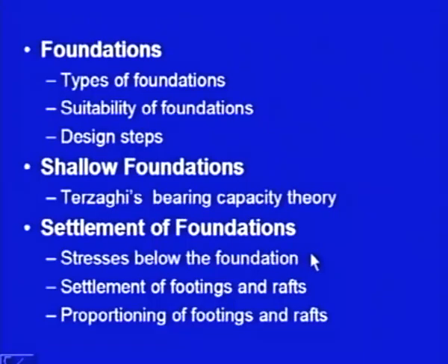For that purpose, we shall need the stresses, that is, how the distribution of stresses takes place below the foundations. Then we shall discuss in detail how to calculate the settlement of footings and rafts, and then proportioning. Once all these things are available, then for a particular type of loading, we will discuss how to proportion the footing and how to proportion the rafts.